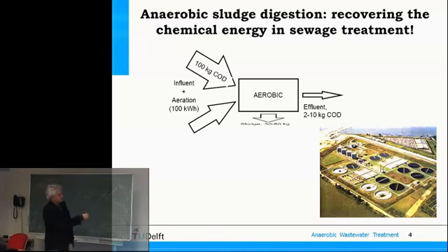This oxidation reaction is very energetic, so a lot of energy comes free. This energy is turned partly into new sludge and partly into heat loss. A sewage treatment plant handles dilute wastewater, so it doesn't really heat up, because there's not too much COD present in sewage. But you can imagine that with a concentrated industrial wastewater, the reaction would even heat up the reactor.